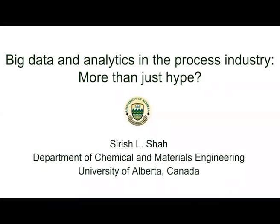So the application that I showed you, the two applications, the one related to Eastman Chemicals and the other on the ABB data set, those were done. We arrived at the pathway using causality analysis, in one case transfer entropy, and in the second case binary database causality analysis. And then we manually concluded that the root cause of the abnormality in both instances were the loops or the variables at the very top. I'm not sure if that answers the question. If not, please do get back to me.